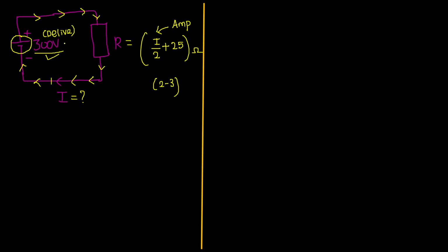And the second conclusion, how will you identify the direction of the current? If a person is delivering the power, then for that element the current entering point should be minus, and the leaving point should be plus. So this will be the direction of the current. So the direction of the given current and the actual direction are both the same. They have given the current direction in the correct way. This is the correct direction of the current. Next, we all know a resistor is a passive element. For the resistor, the current entering point should be plus, and the leaving point should be minus. Yes, sir. Now, I would like to know the voltage drop across the resistor.